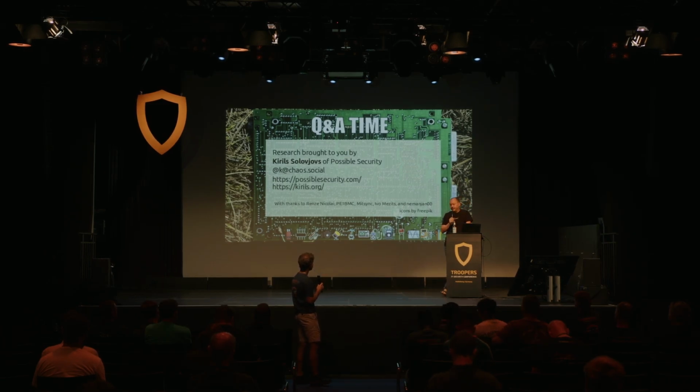Yeah, exactly that. You're exactly correct. According to the installation documentation, if you have more than, I don't remember the number, I think more than 40 or 50 apartments, you're supposed to use signal separators in between for some reason. But yes, in an installation with fewer apartments than that, it's just one bus going everywhere, and if you short it at one end, then you're done. I think you might even be able to burn out the power supply that way. I haven't tried it, of course.